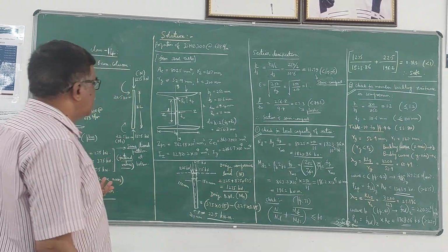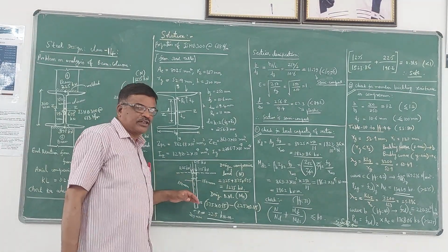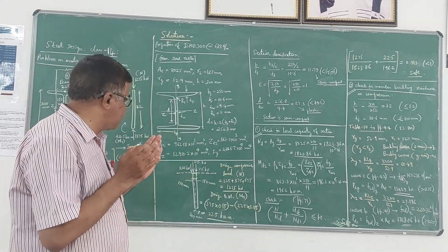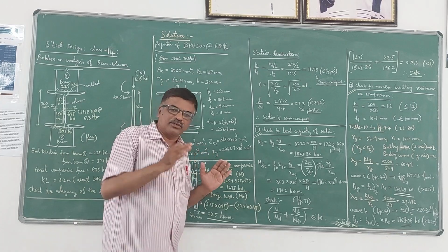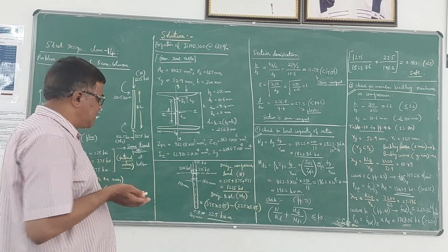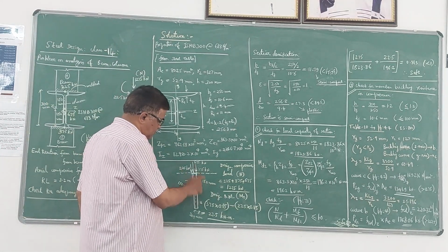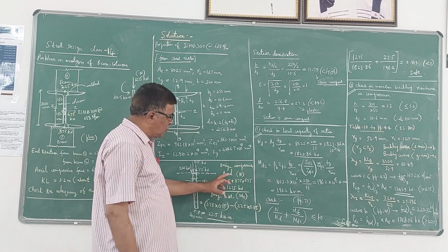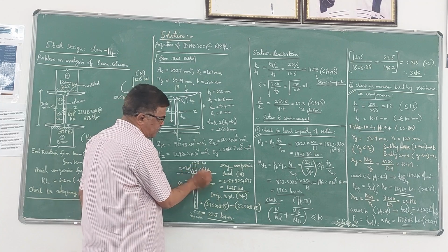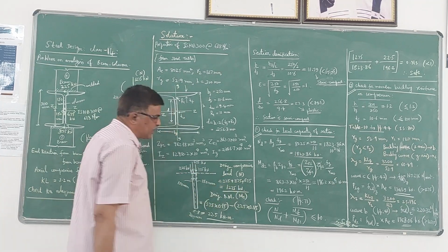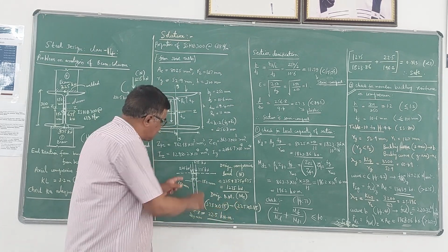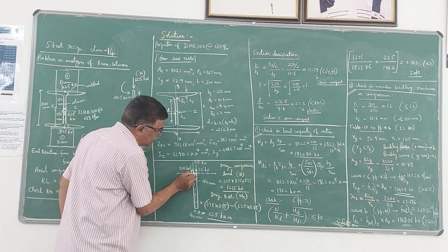So what you have to do is, first calculate the actual compressive axial force coming on that beam column, and also the moment due to the eccentric loads. Here this beam column has to be designed for a total load of 225 plus 375 plus 675. So that is 1275 kilonewton. That value I am going to take as N. Then moment also will be there because these are eccentric loads. So you have to take the moment about this point.